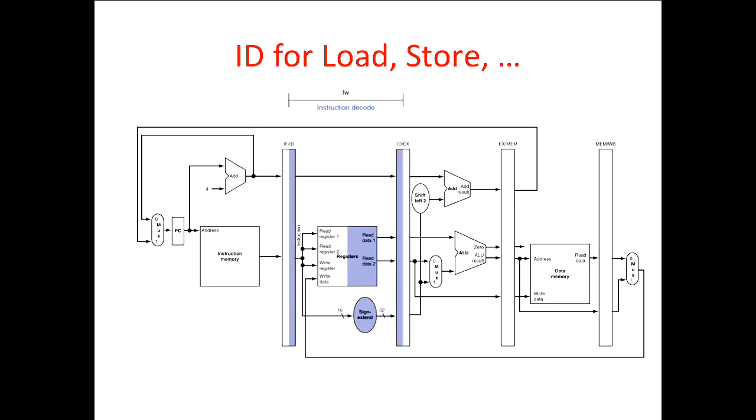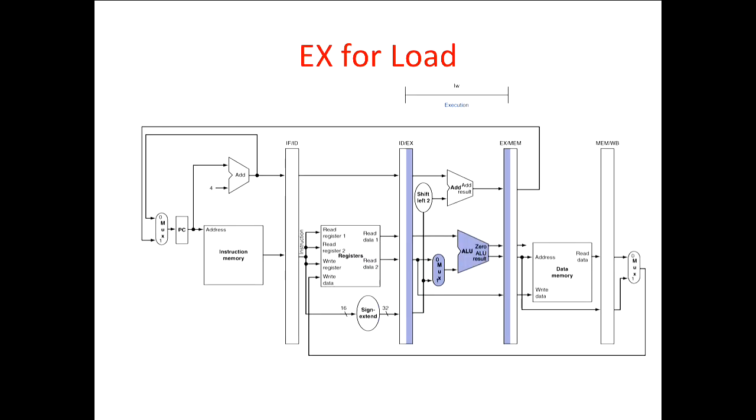So now that first instruction moves to the next clock cycle, and we do the decode for the next instruction. It's sitting in this register. We do things like sign extend the immediate in here. We also read the 2 register operands, and we capture all those in more registers. You have these registers just to capture the data we've got. We haven't done any compute on this yet. All we're going to do in this clock cycle is decode, read the register operands and capture them here.